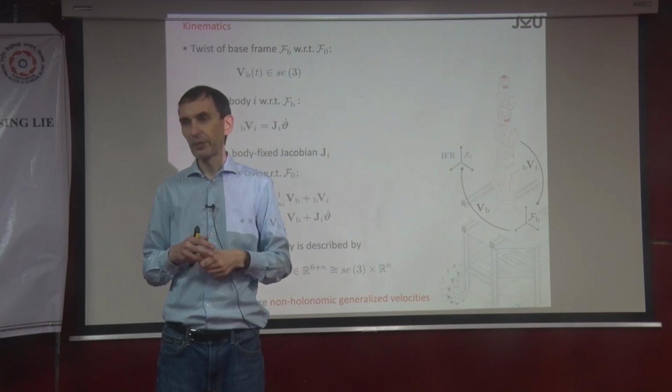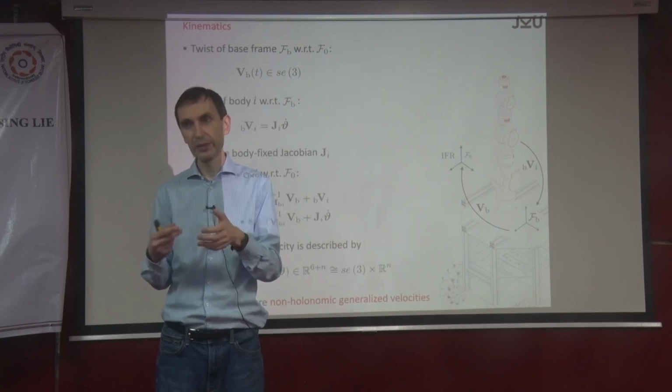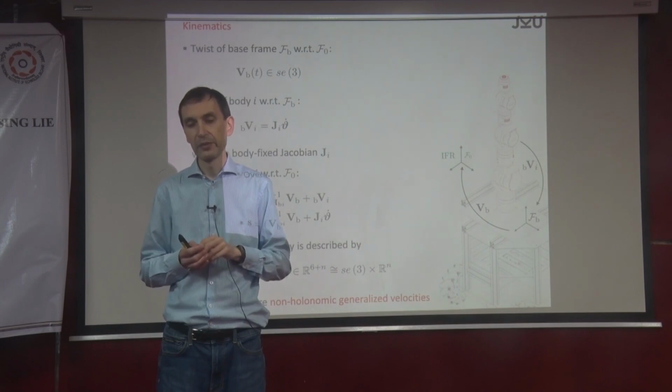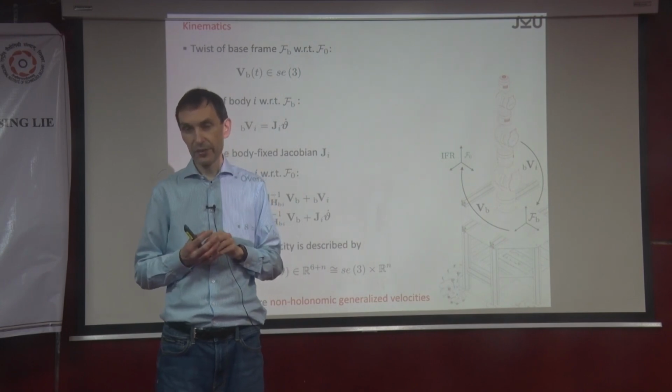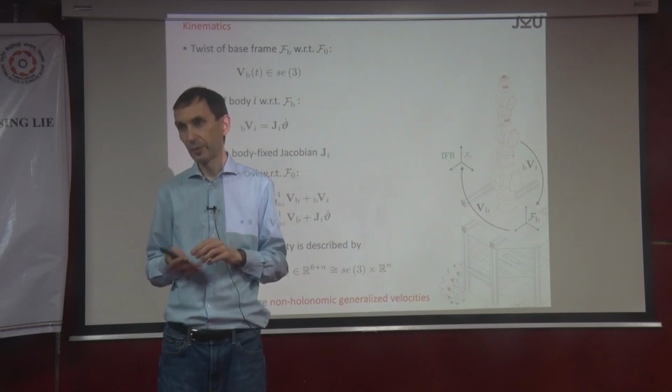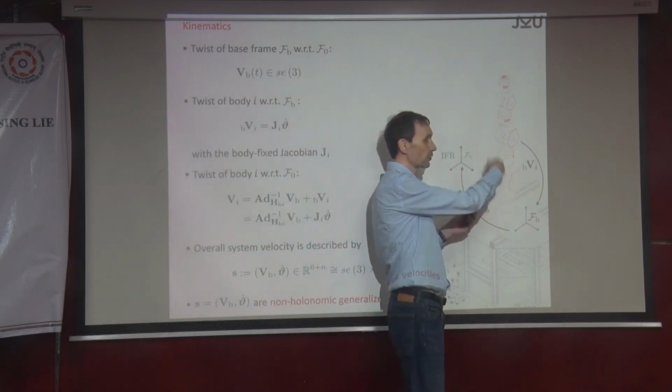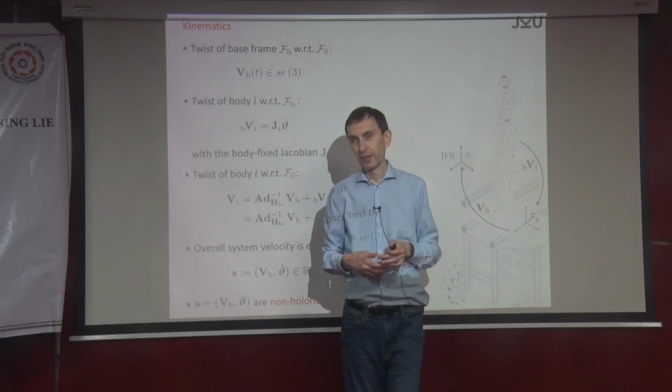What you most of the time really get is the motor current, and that is somehow related, usually linearly by some motor constant, to the torque. So let's assume, and that is the case for most robots, that you can measure the torque. And when I say the torque, I mean the drive torque, right? So you actuate your joints.